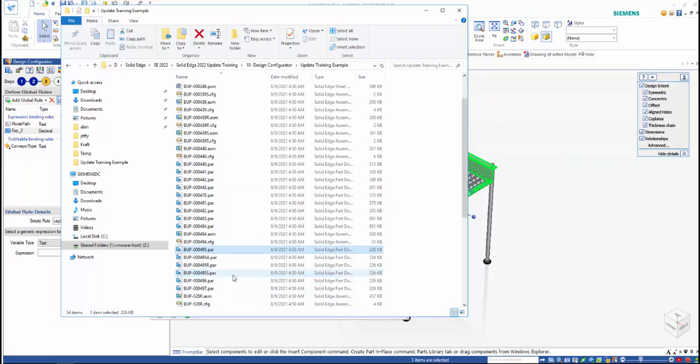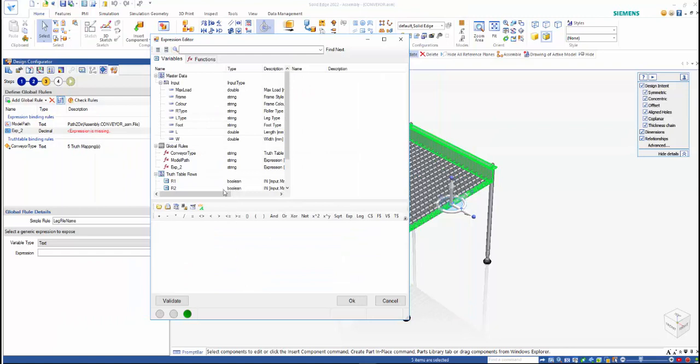You'll notice that we've got files for both of the models. So we're going to utilize what we have for that. If we put this in quotes because it's a text string, and then we want to add them together, so we'll use the plus sign and input leg type, and we need to add the .par onto the end there.